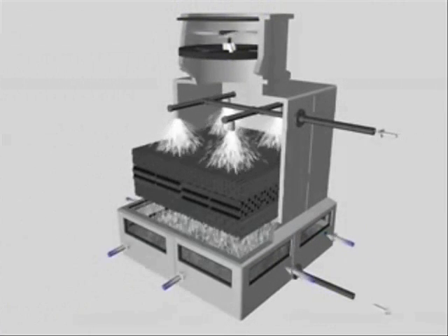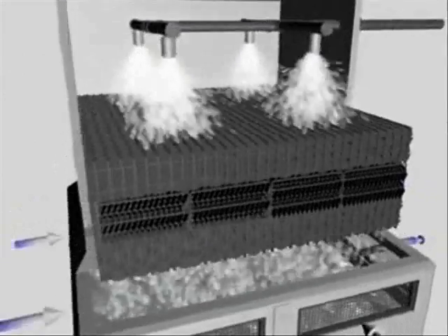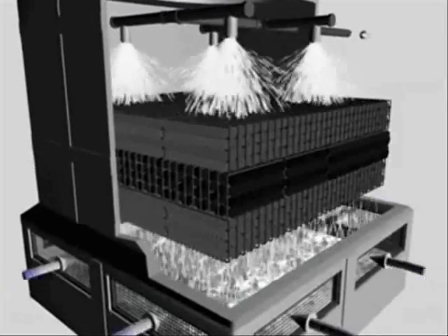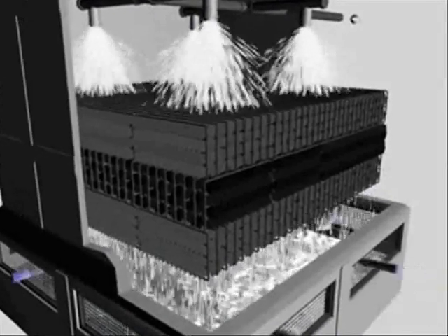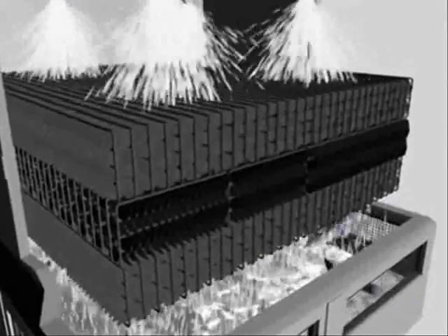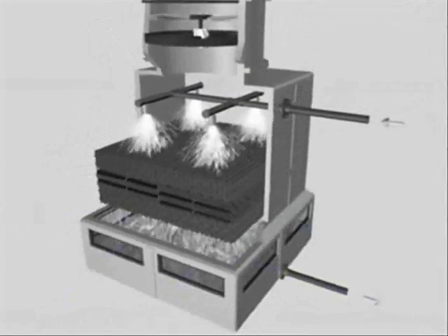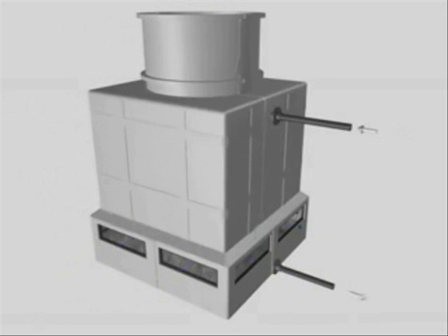Water enters at the top part of the tower and is sprayed via nozzles so that it is uniformly distributed and effectively wets the fill. This is an example of an induced draft counterflow cooling tower. In this type of cooling tower, water is exposed to a mass of air induced by a fan at the discharge, coming from the bottom air inlet. The cooled water is received by the basin that is connected to the tower discharge. This is the cooling tower.